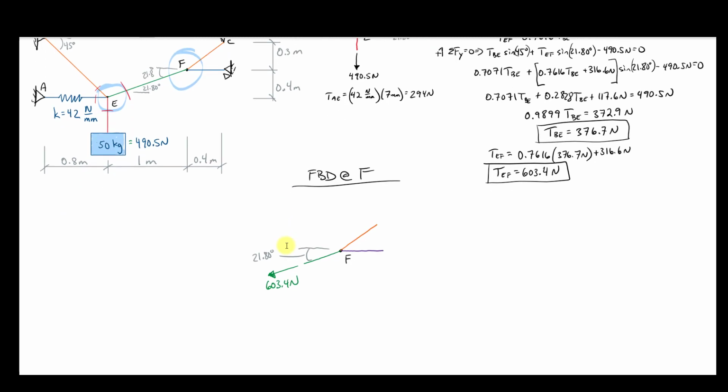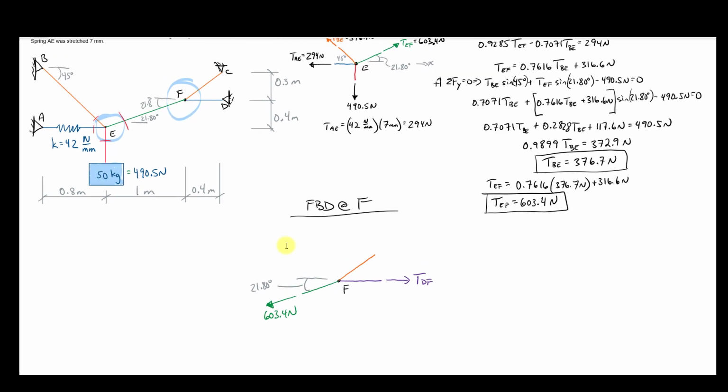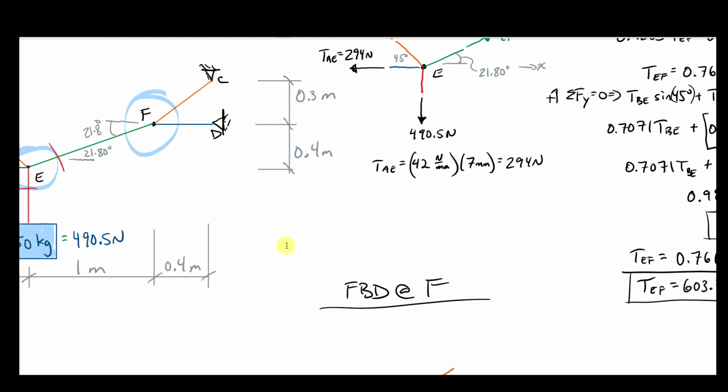So that's cool. Now DF here, we know it's going straight, so we don't really need to do any angle work. We already know it, but I do need to write my vector there. And then I've also got my angle here to the orange line. And I picked this to kind of show you something interesting. If this is 0.3 tall and this is 0.4 meters wide, then what is this length right here? We know this to be 0.5 meters long. It's a 3, 4, 5 Pythagorean triple.